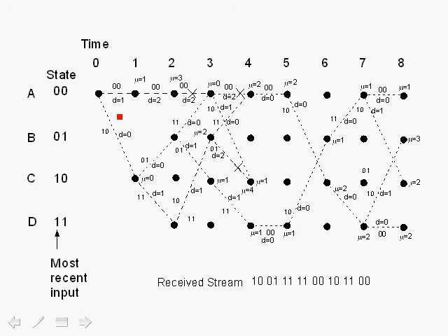The way the Viterbi decoder works is, given that we always start at the all zero state, we assume that we either received a 0 or a 1. So we move from state 0, in the case that we received a 1, to state 1, 0, just going through the Trellis diagram. Straightforward. Of course, if that was the case, then the output of the convolutional encoder would have been 1, 0. We compare that with the received stream, which is 1, 0. And we compute the Hamming distance between these two, and it's of course equal to 0 since they match. So we set d equals 0, and this is of course the branch metric for this branch right here.